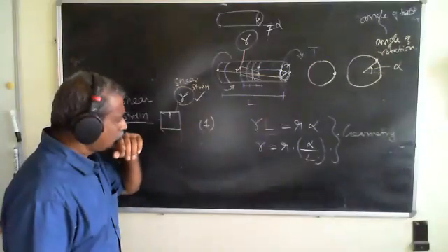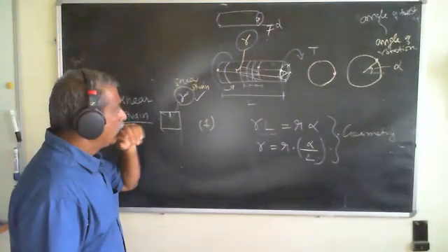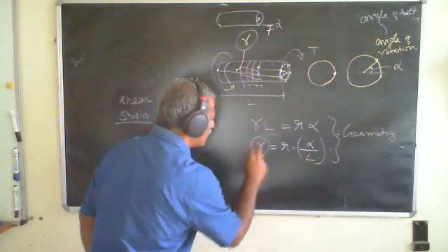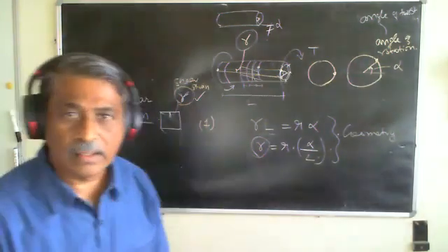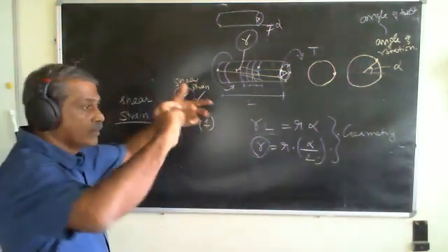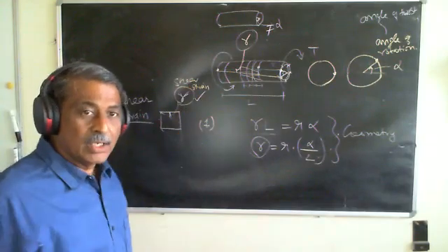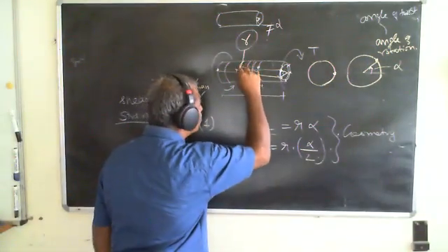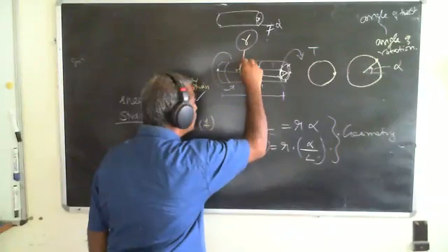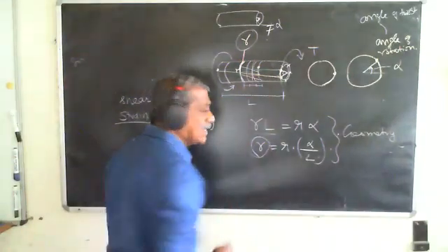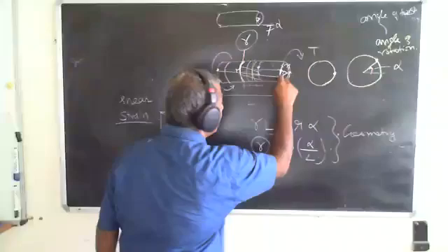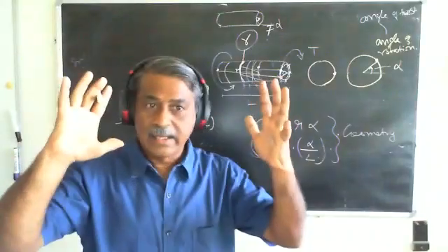All right. Now, what am I looking at? I'm able to find out that there is a shear strain that has occurred because of this deformation, which is a twisting deformation. I also find that there is no change in any of these, as if every cross section here, every ring over here, is like a rigid body rotating.